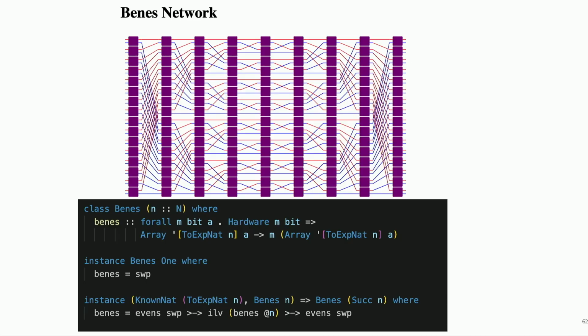So with these two programs, I can run a standard industry tool called a logical equivalence checker. It's a formal verification tool, and it takes two circuits and can tell you if they're the same or not. I ran that tool, and the proof went through, and it verified that the engineers' implementation matched the SystemVerilog code that I generated. The SystemVerilog code was isomorphic to the picture. So I had done the verification. That was kind of cute.